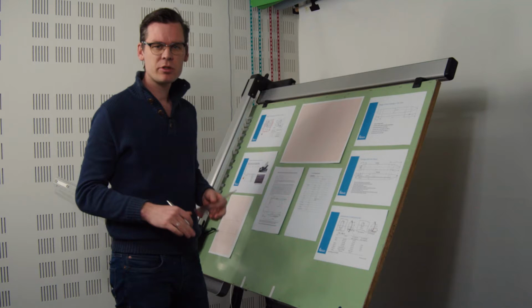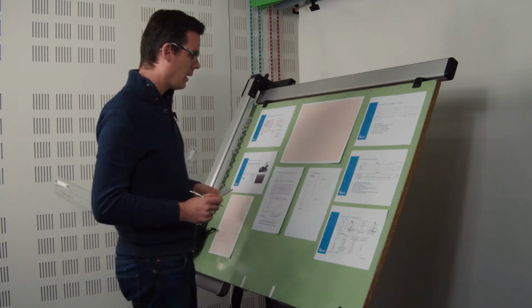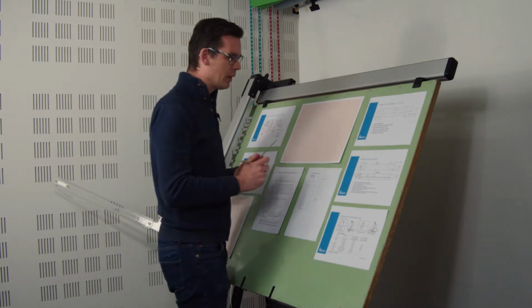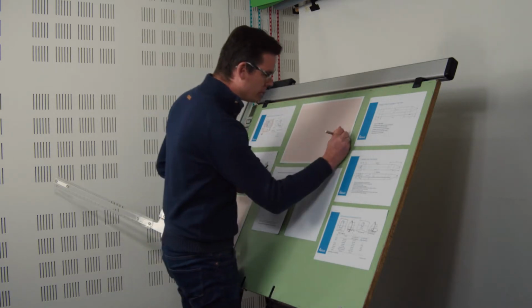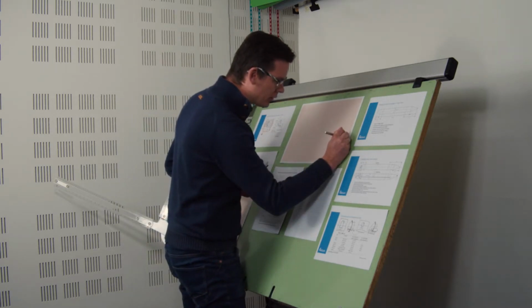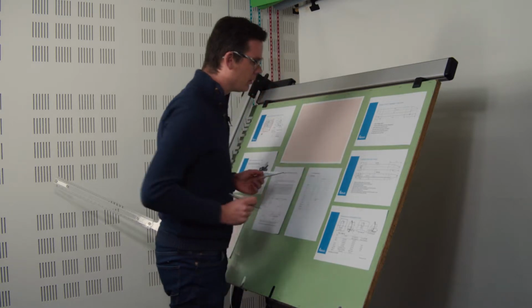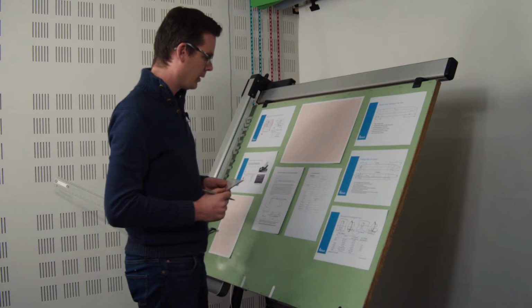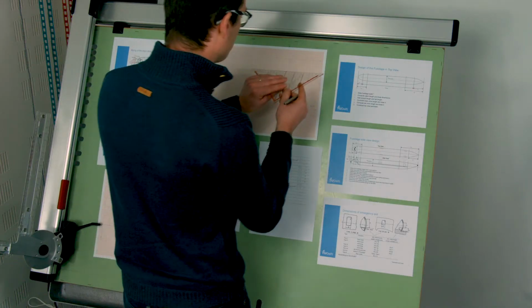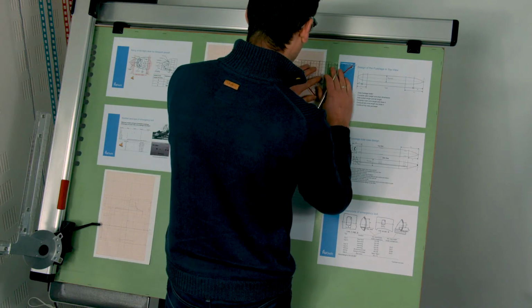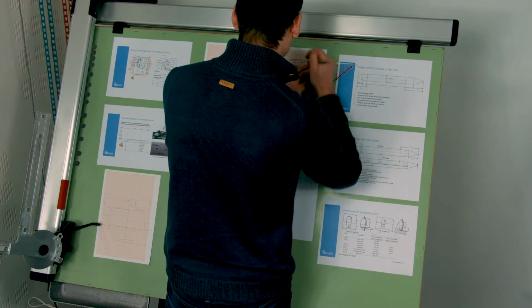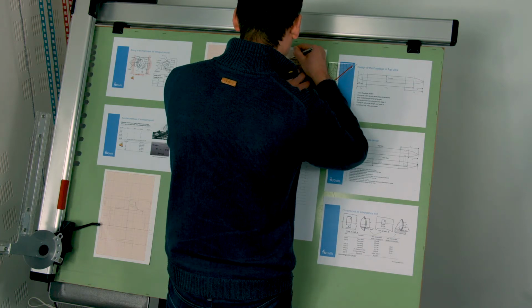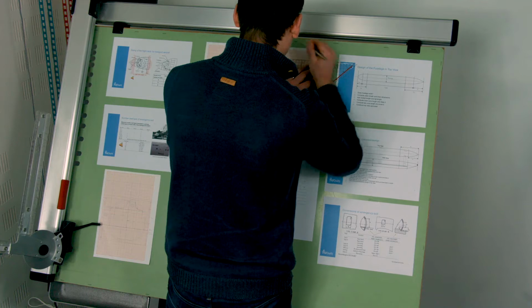The length of the tail cone says here is 10.3 meters, and we are drawing everything at a scale, I didn't say that yet, at a scale of 1 to 100. It's a very convenient scale. That means every meter is a centimeter on my drawing. So 10.3 meters comes down to 10.3 centimeters. That's somewhere over here. I'm marking that off here.